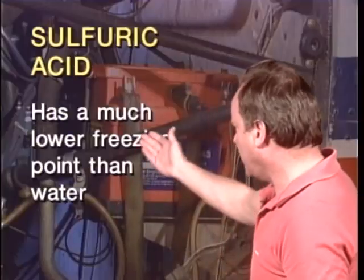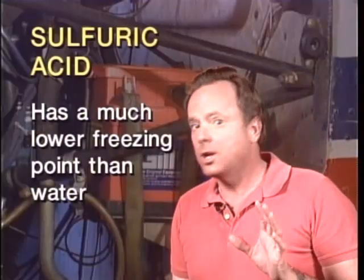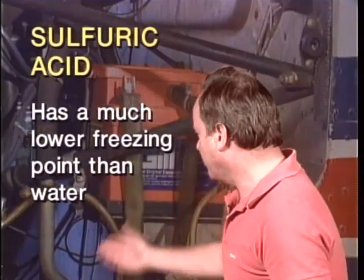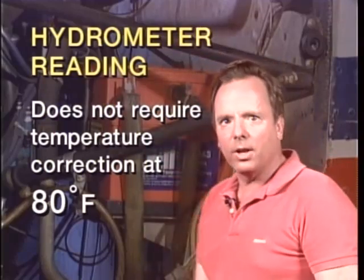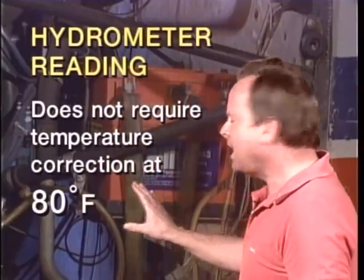Now let's talk about some specifics they ask you about lead-acid batteries. First of all, they want you to know that the sulfuric acid used as an electrolyte in there has a much lower freezing point than water. And what that tells you is a fully charged lead-acid battery will not freeze until extremely low temperatures are reached, because most of the solution is acid, and sulfuric acid has a much lower freezing point than water. Another question they ask you about is a hydrometer reading. You can measure the charge of a lead-acid battery by measuring the specific gravity of the electrolyte with a hydrometer. And they want you to know that a hydrometer reading does not require a temperature correction at 80 degrees Fahrenheit.